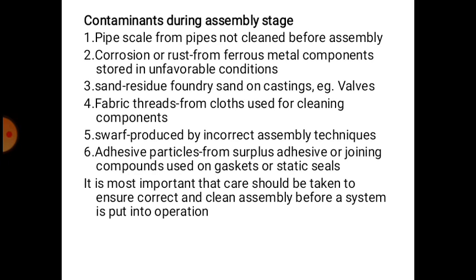Contaminants during assembly stage. Pipe scale from pipes not cleaned before assembly. Corrosion or rust from ferrous metal components stored in unfavorable condition. Sand residue, foundry sand on castings.